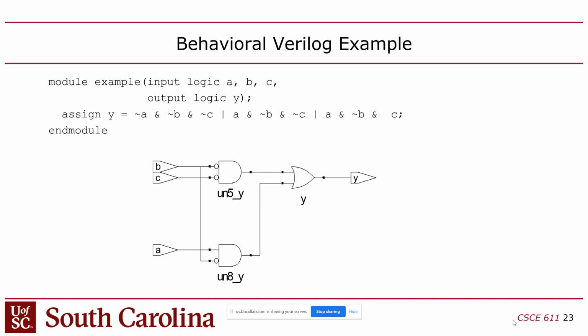And then this is another screenshot from the book, but this actually came out of the Quartus tool that we're using. And this is fascinating to me because it's really cool how it takes this code, and in this case it's not that big of a deal because it's just binary Boolean logic, but in general it's going to get compiled, not into machine code as C would, but into this. This is actually the output of the compiler. It's a gate level netlist.